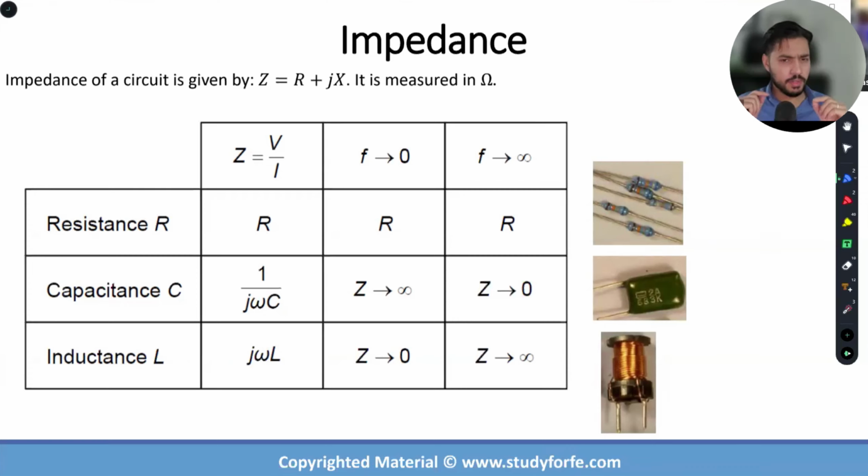Make sense? Because the fact of the matter is that impedance is actually an umbrella term that we use, which encompasses your resistance, your capacitance, and inductance. And more precisely, it packages your resistance and your reactance. The title of the webinar is Impedance, Resistance, and Reactance because reactance is capturing the effect of capacitance and inductance. So when we think about impedance, interpreting impedance as resistance is probably a decent start, but it is inaccurate.